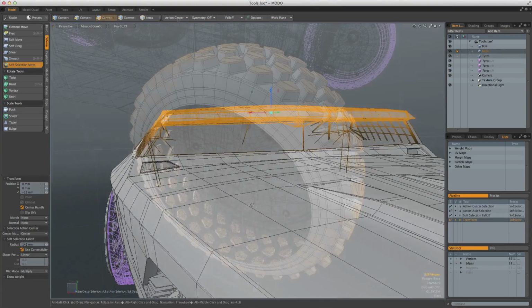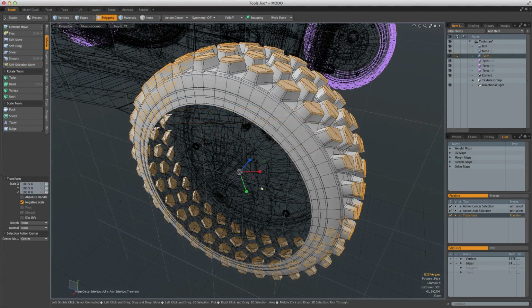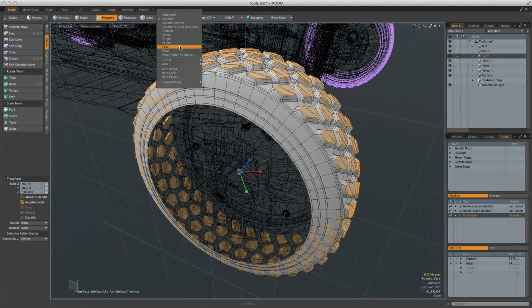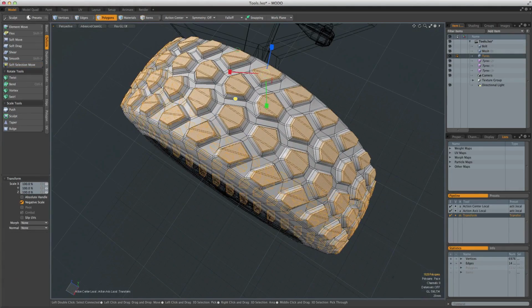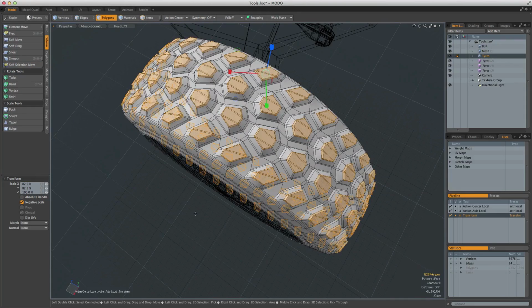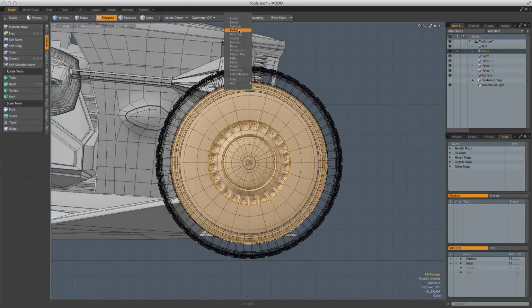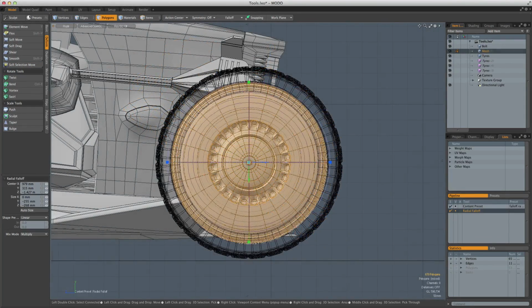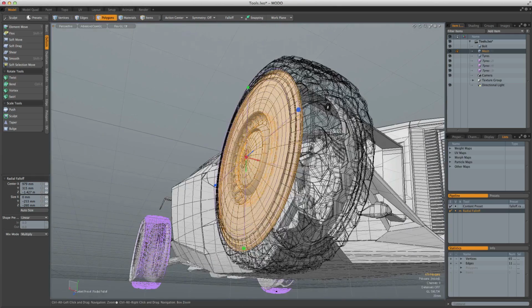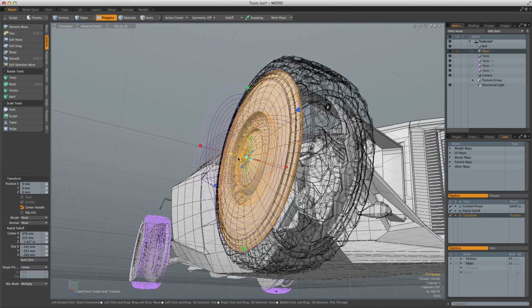more powerful tools. Action centres, or custom tool pivots, are a set of modifiers that allow you to change the position at which a tool will operate, and also how the tool handle should be aligned. Fall-offs are methods of modulating the effect of a modelling operation, and remain live while the tool is running, so deformations can be intuitively tweaked.